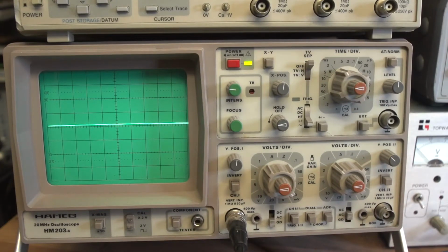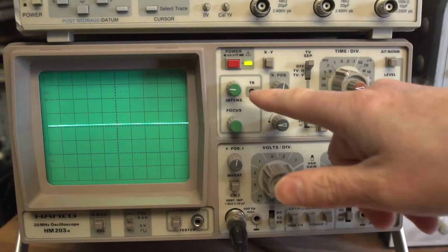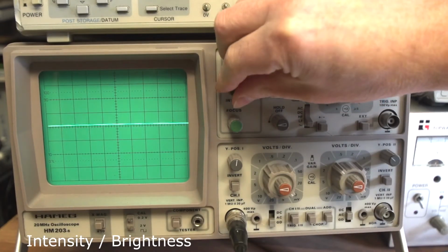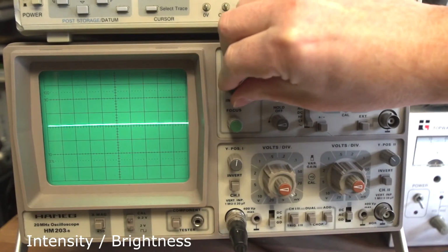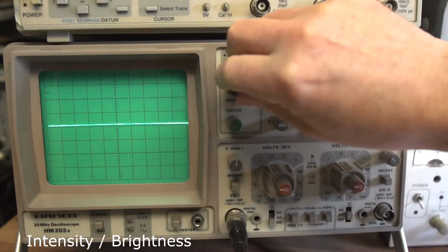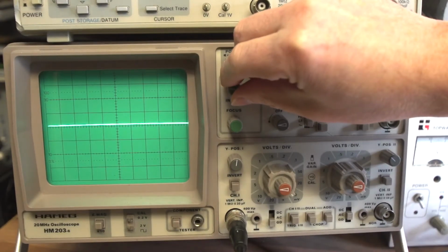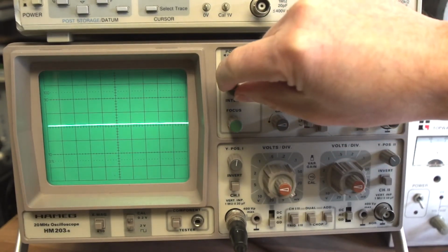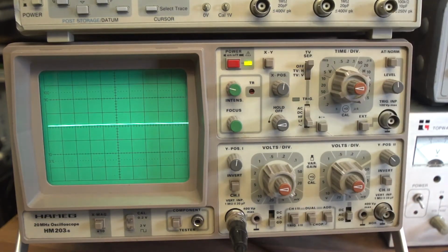Here's a quick rundown of the controls of the scope. I'm not going to go into every single control and knob, but the main important ones. First of all, you've got an intensity here. This is just for brightness, so you can turn the trace down, turn the trace up, just set it to a comfortable position. You don't want it too bright because you can damage the screen on these CRT type old version oscilloscopes. If you've got a modern one, you don't really have a brightness control. It's all done on an LCD panel or on a PC computer.